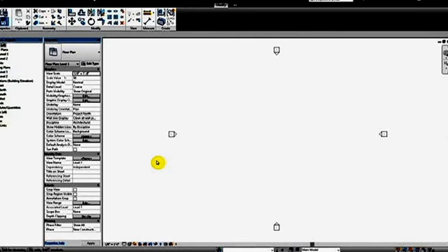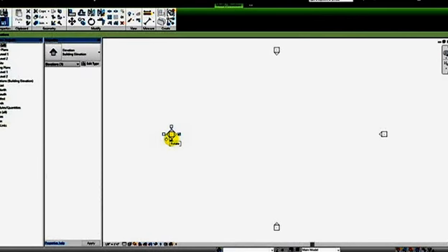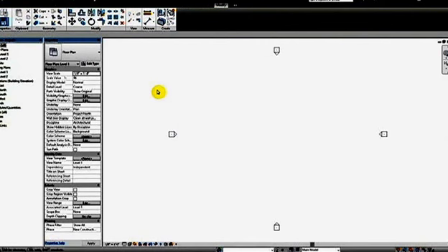And now last but not least, there's this final toolbar down here at the bottom. Again, not sure what it's called, but you have this text over here on the left. This is almost like the Autodesk command line, except you can't type in it. It just shows you information about it. So like if I select this, or if I hover over it, it tells me, oh, that's elevation 3. I selected it, I can rotate it. If I start a function, it'll tell me what the next step is. So it's kind of like the command line in the fact that it tells you what's next and what you have highlighted, but you can't enter any information into it.